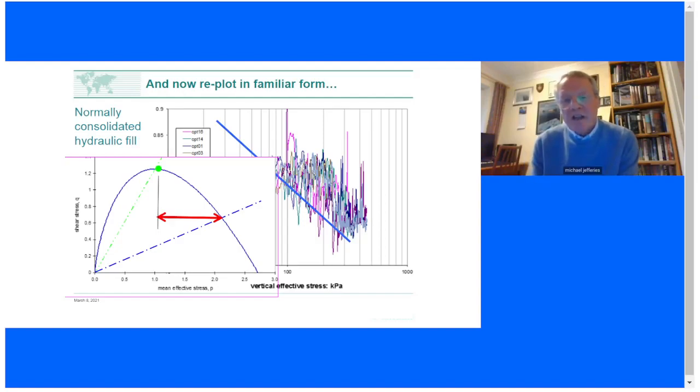When you do confined consolidation, your stress path on a q-p plot is more or less where I've drawn that dotted blue line. It depends on the material properties, but it'll be in that order. And the point of this is that where that blue line crosses the yield surface, that is where your normal consolidation locus is. So the corollary of what I'm observing here with my CPT is I've got a wide range of those normal consolidation locuses.